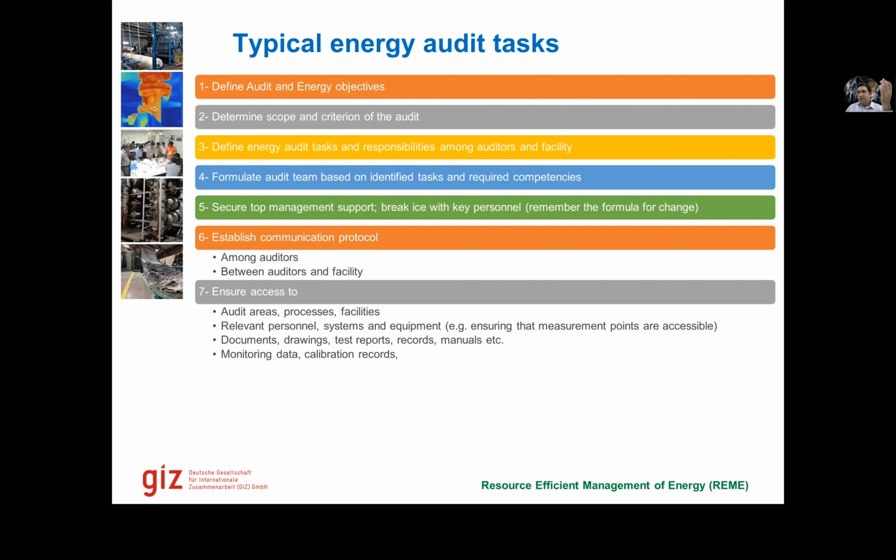And we requested them to get it done with the main vendor who installed the PLC, because if we would do it, we would have to install a separate PLC. So it is important for us to see what we can do and what we cannot do. If we want to do a stack analysis, ensure already that there are points available there for inserting the probe. If you want to do flow measurements, ensure that you are able to install your meter there.